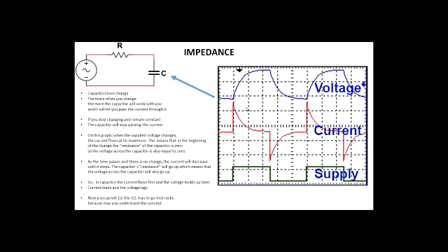Now, one thing I want you to notice is that with the capacitor, because it acts as a short circuit, the current is first. That's an important concept I'm trying to give you here. It is going to help you with other subjects. Okay? So in the capacitor, we have current happening first, and then after that, we have voltage happening across the capacitor. Again, the current is first, and the voltage happens second. So you can say that the current leads the voltage in the capacitor, or the voltage lags with reference to current. Okay? So that's the capacitor circuit.